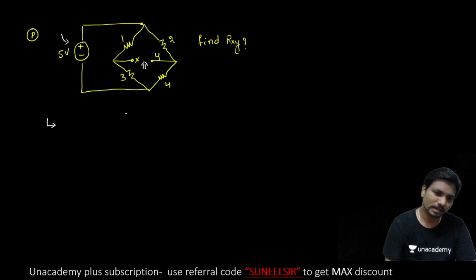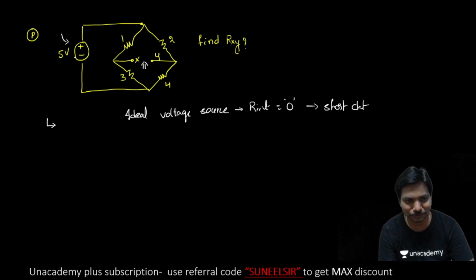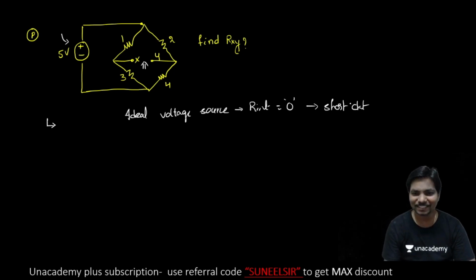We know very well that in the case of an ideal voltage source, the internal resistance is 0, and 0 means a short circuit. So wherever we have a voltage source, we have to short it.